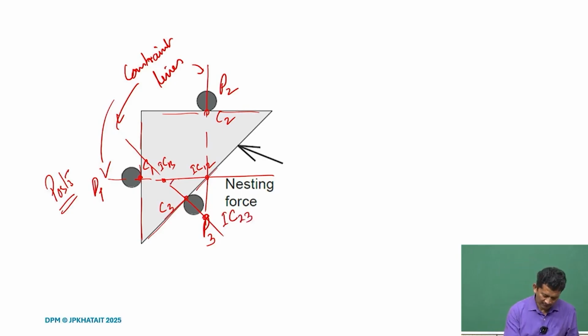What we also realize is that if we extend the constraint lines, and they enclose an area, so if it forms some kind of triangle, then we can prove and easily see that there is no over constraint and the system is exactly constrained.